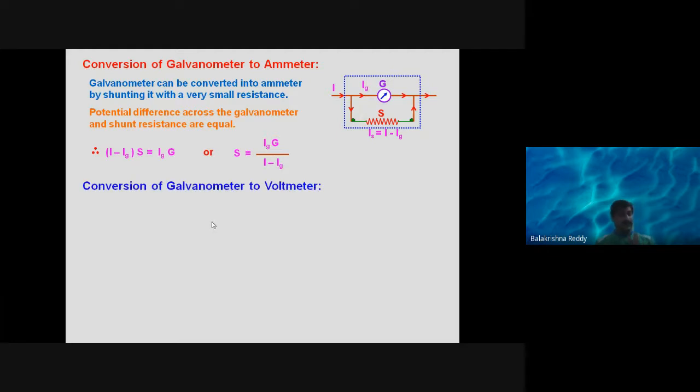Now, here is how we have converted a galvanometer into an ammeter. We are indirectly dividing the resistance, and with respect to that, we are also managing the current here. Therefore, we can easily measure current from the galvanometer, meaning the galvanometer is acting as an ammeter here, just because of the nearly equal or small resistance connected in parallel. Then this total is called an ammeter now.